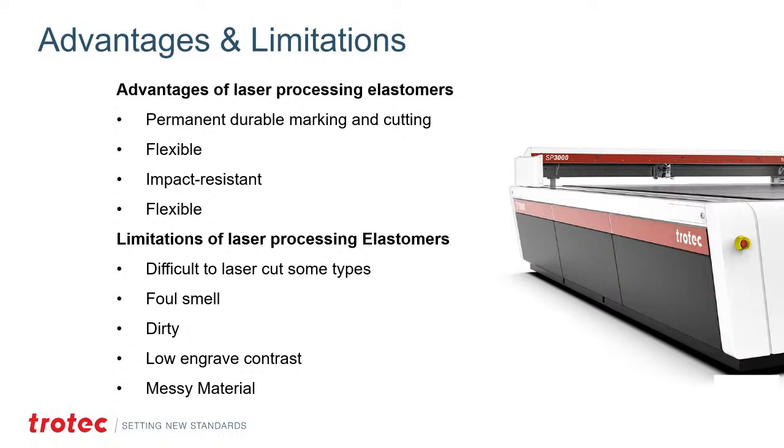If you don't have enough laser power, you may find that you will not cut through it. But yet 10 more watts and you're cutting through beautifully and the edge quality is great. So that is something that you need to understand on some different types of rubber.